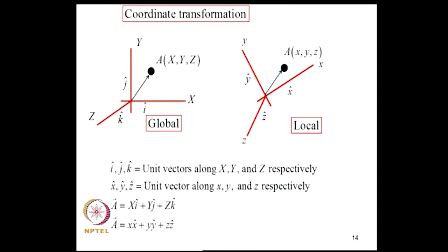Now, the next question that we need to answer is what happens if the local coordinate axis for the beam element does not coincide with the global coordinate system, which invariably happens in most applications. So, to be able to do that, we will now need to develop the rotation matrix in 3 dimensions. So, we will quickly run through these ideas here.